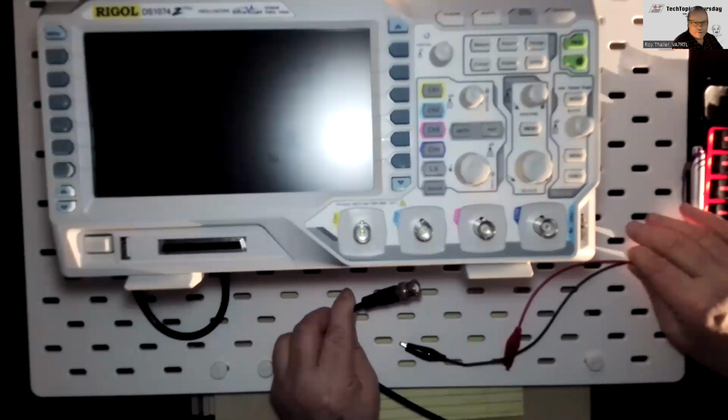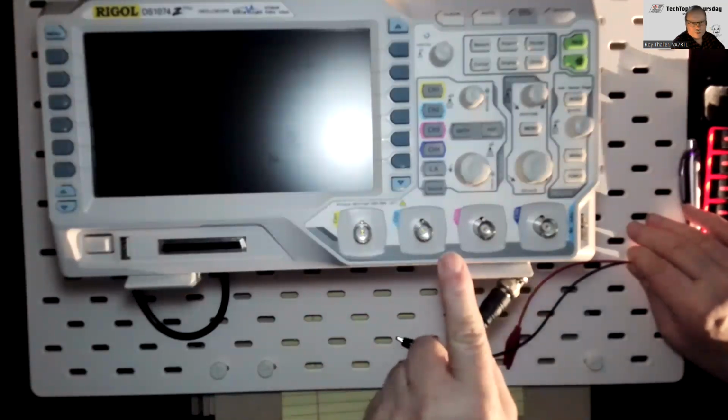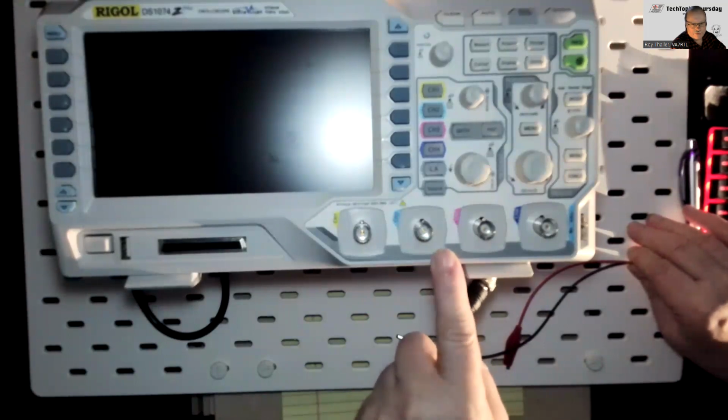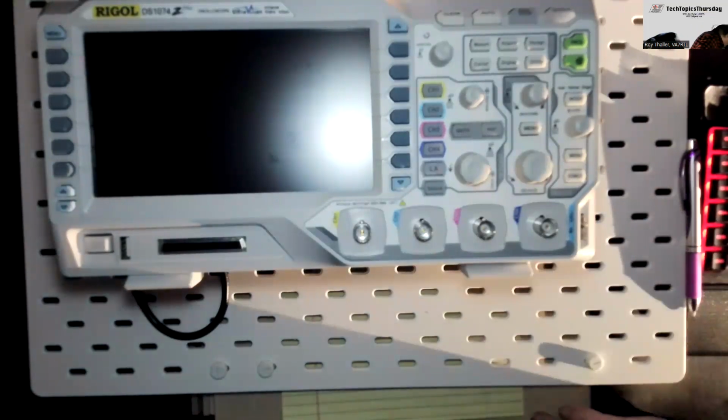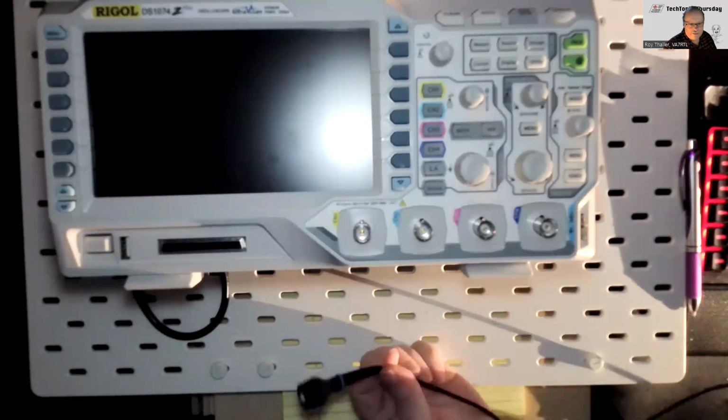Now, most likely you're going to run into some impedance problems with this, because the impedance of your line is 50 ohms, and typically the input of the scope is 1 megaohm, unless you get some of the newer, more expensive scopes where you can adjust it from 50 ohms to 1 megaohm. So that's one of the things you have to look at. What's recommended is to use the scope probe that comes with the scope. Your end connector here is a BNC, and it's shielded, so if you happen to touch it, you don't get a shock.